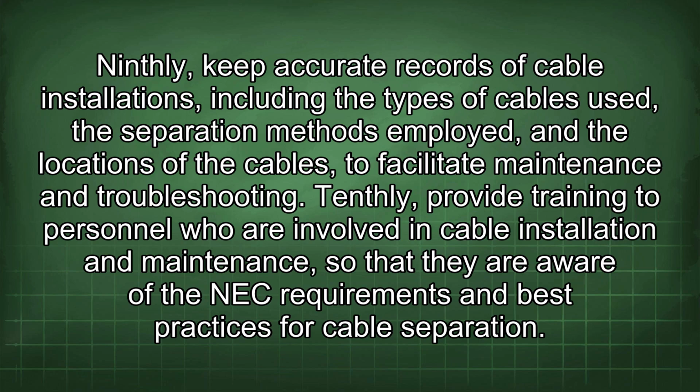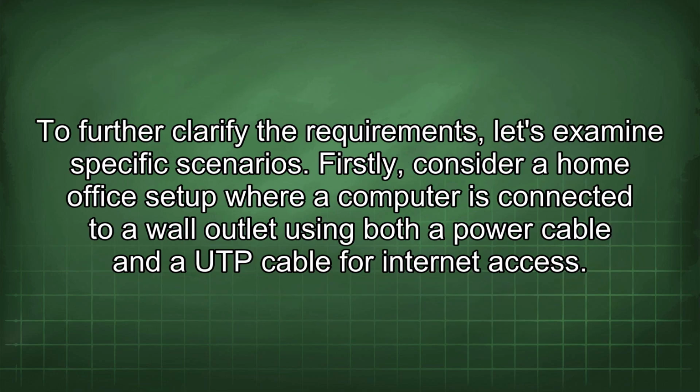Ninthly, keep accurate records of cable installations, including the types of cables used, the separation methods employed, and the locations of the cables to facilitate maintenance and troubleshooting. Tenthly, provide training to personnel who are involved in cable installation and maintenance so that they are aware of the NEC requirements and best practices for cable separation. To further clarify the requirements, let's examine specific scenarios.